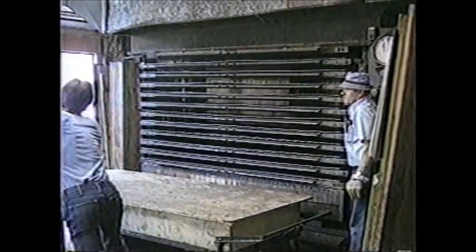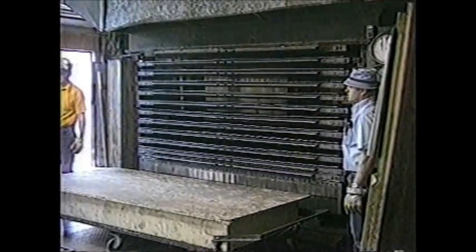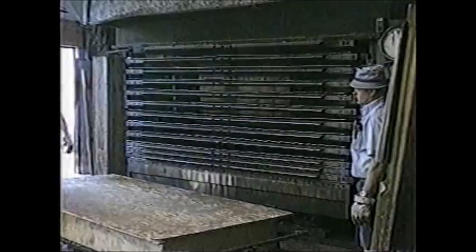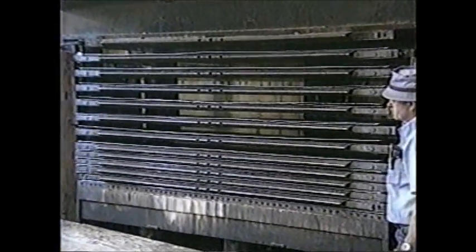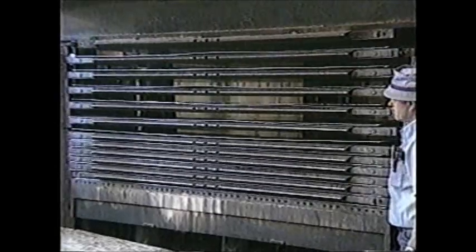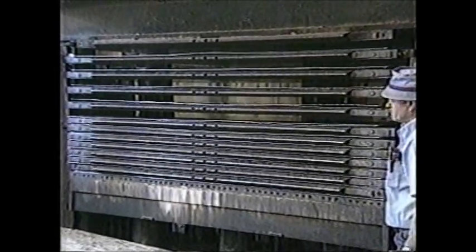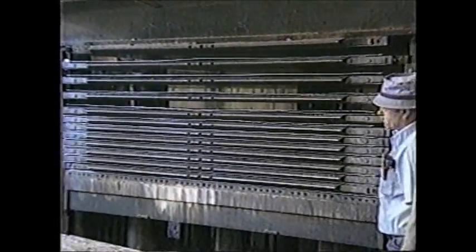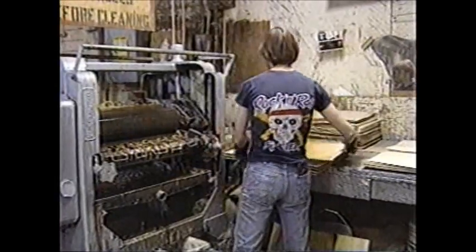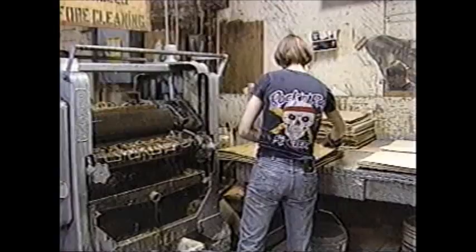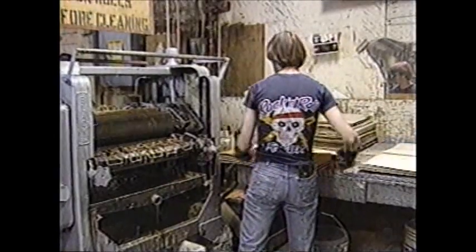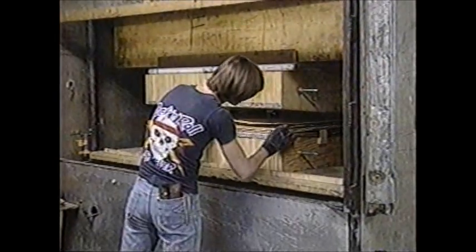After the press is unloaded, the press openings are loaded, each with 2 cauls containing plywood panels. The length of the press cycle is determined by the type of panel being processed. Curved plywood panels are laid up and formed by being cured between male and female molds under heat and pressure.